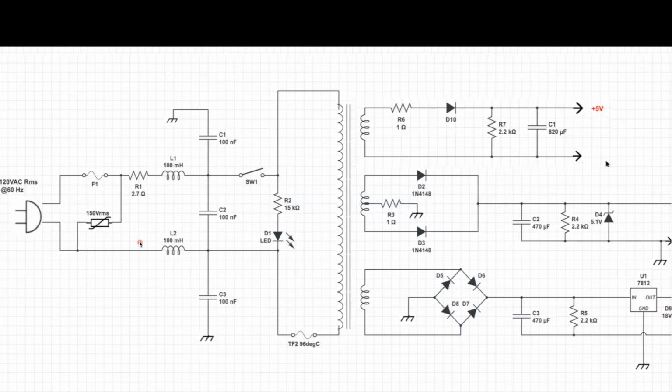A lightning strike. That would be a bad surge, right? You know, maybe lightning hits the power line out front and we get this big surge in our house, and hopefully it protects my very expensive computer or whatever my electronics is attached to. Now, you do realize when this MOV shorts out and blows the fuse, our device is still going to be dead, but only a couple of bucks worth of parts went bad instead of the very expensive parts, like whatever this is powering, my 70-inch TV or my piece of industrial electronics or my super expensive gaming computer or whatever I have.